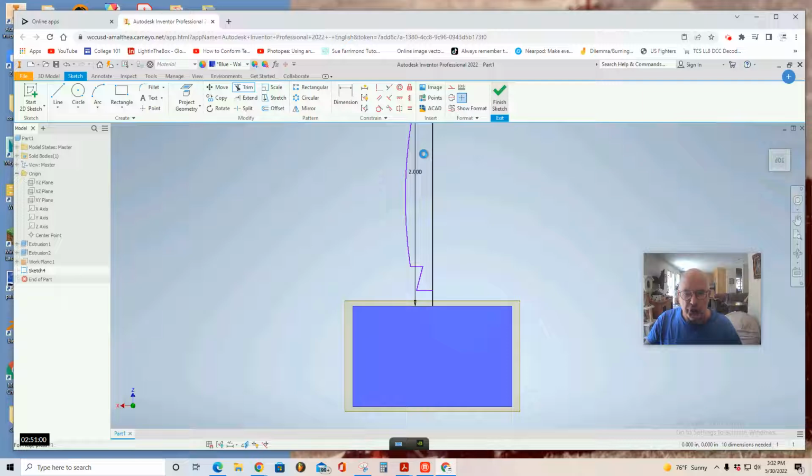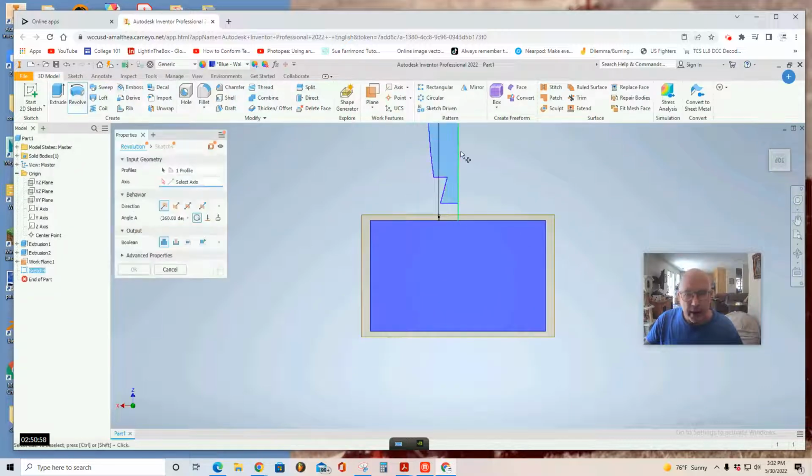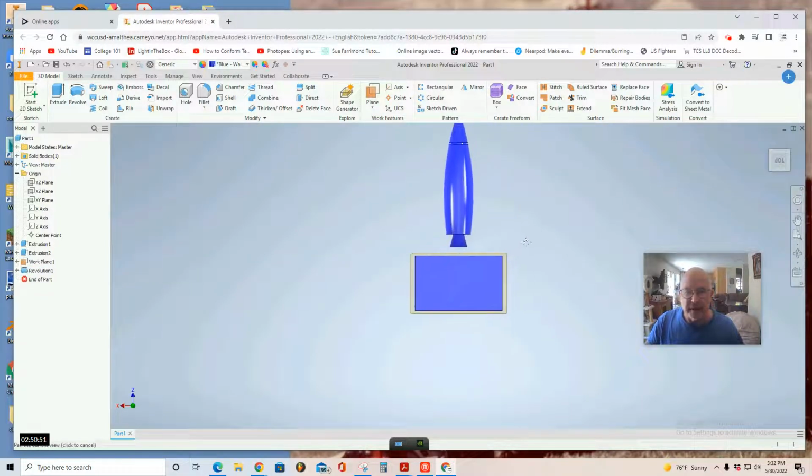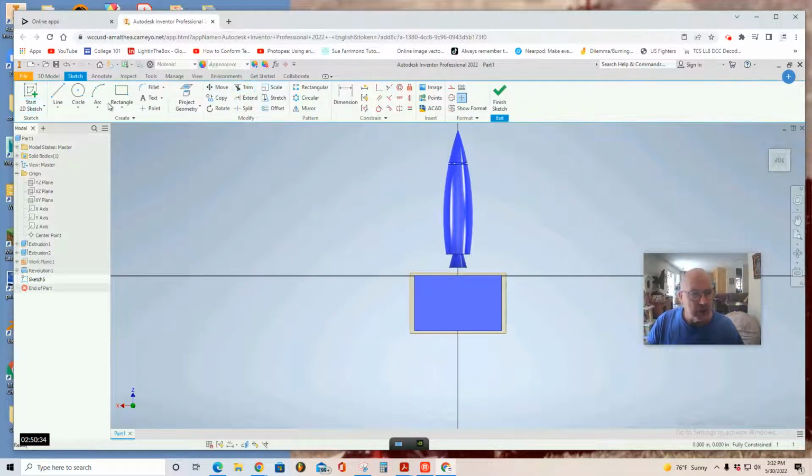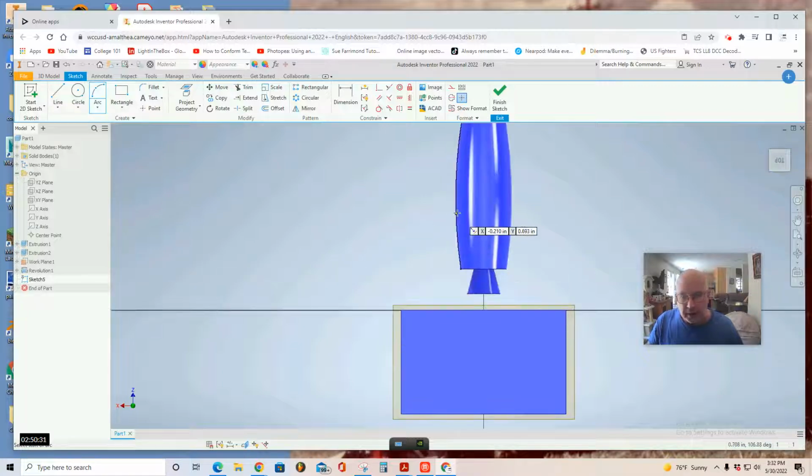So now I want to finish sketch and revolve around the axis, which is my y-axis. And then it's fine, so I click OK. And there I have my first, the fuselage. That's the first portion of my rocket. I can use the same plane to create the fins. So I start a 2D sketch. Remember, click on the perimeter line of your work plane to activate it. Click. And then I'll go to the arc tool, and I'm going to create that curved retro fin appeal.